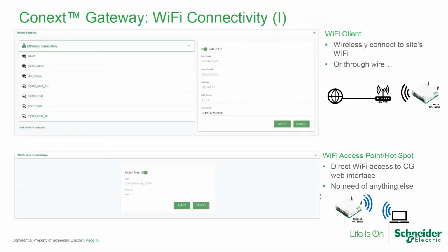So you're able to pull via the TCP/IP port, the Ethernet port of the gateway unit, every single device on any one of the various communication networks inside of the gateway, which makes it very interesting for someone who wants to connect this to a DCS, for example.